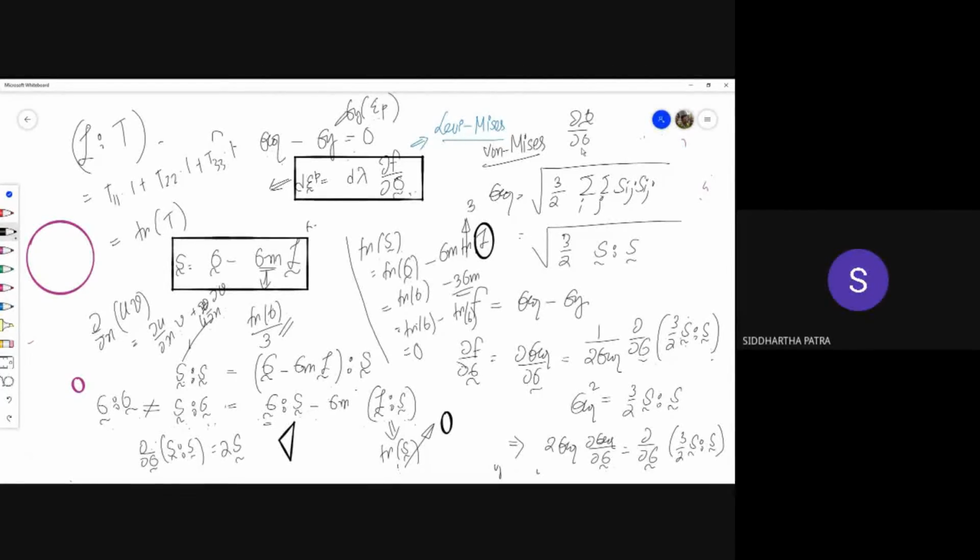Del sigma is the identity matrix. So essentially you have the deviatoric stress, and it's not the identity matrix in second order, it's a fourth order identity matrix. So when multiplied with S, this simply gives you S, but you could have also represented it as S times sigma, like u times del v del x right here.